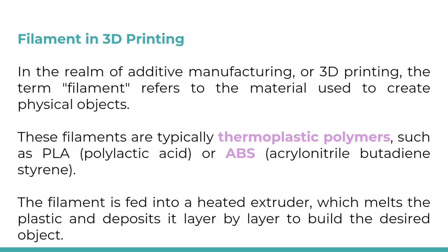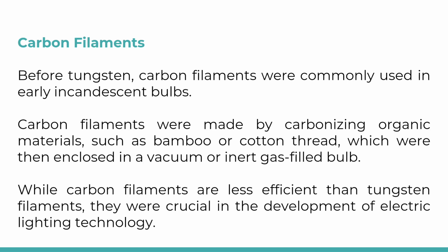Filament in 3D printing. In the realm of additive manufacturing, or 3D printing, the term filament refers to the material used to create physical objects. These filaments are typically thermoplastic polymers, such as PLA, polylactic acid, or ABS, acrylonitrile butadiene styrene. The filament is fed into a heated extruder, which melts the plastic and deposits it layer by layer to build the desired object.